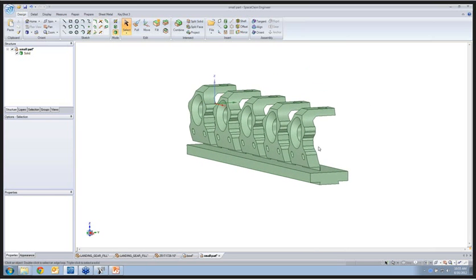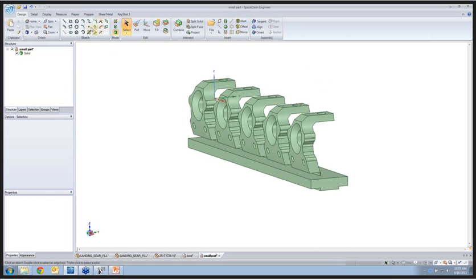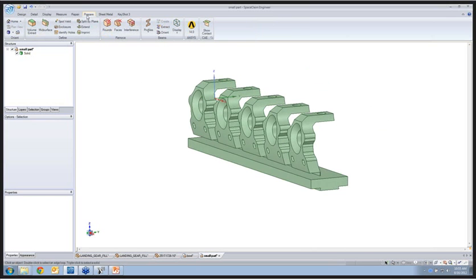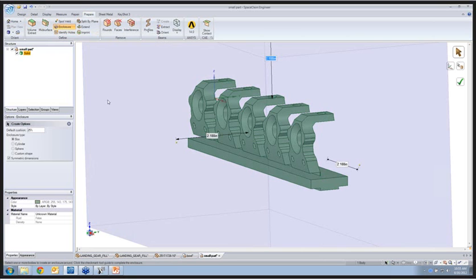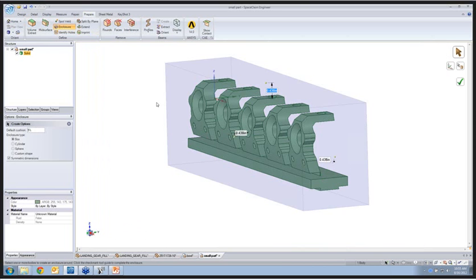The last thing I might want to do is send over to MasterCam the stock model from which this comes. There's 6 ways to create that. In SpaceClaim, you could do it the way I've been showing you, where I take edges, pull on things, or even create a sketch and pull that out to make a solid. I'm going to use a different method, using a tool we have called an enclosure. And it builds a solid right around whatever solid I select. It builds a brand new solid.